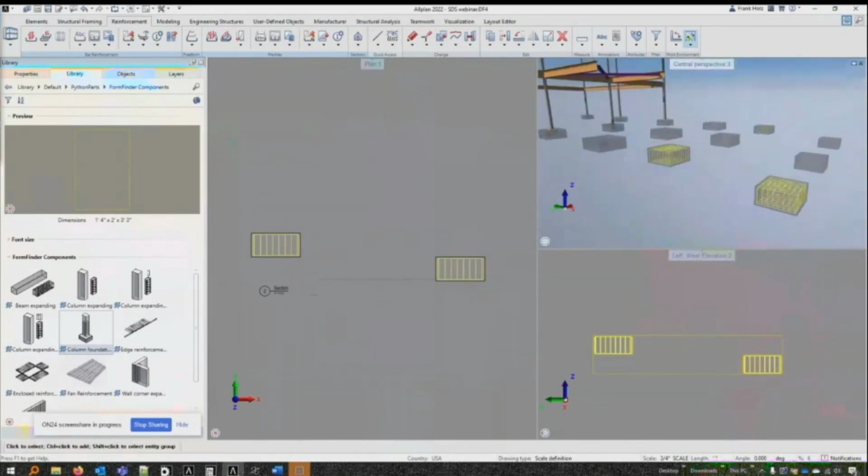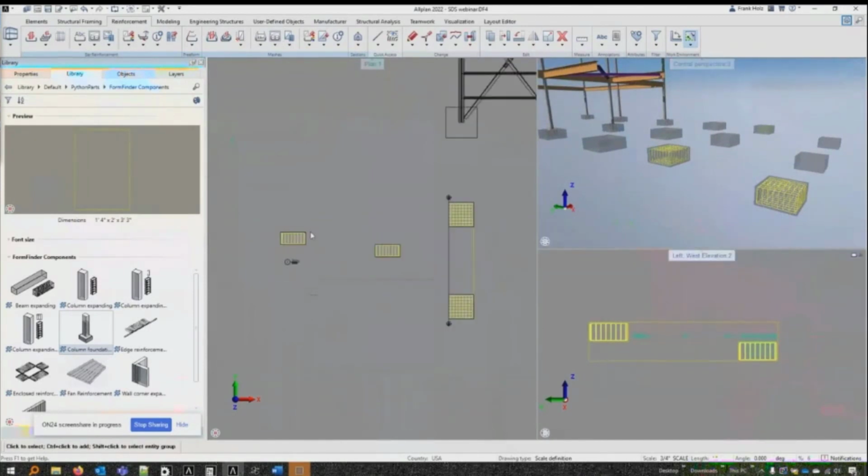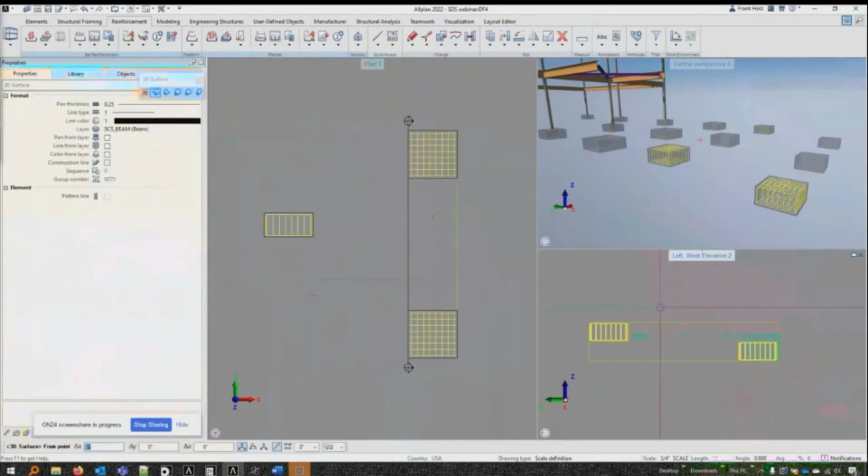All right, so now I'm going to create some fresh model here. This is going to be my step footing. So to do that, I'm going to come here to my west elevation and just start drawing in my 3D model. And I'm going to use a 3D surface tool. You'll notice it's right at the center. This is just where my elevation is being taken. I can move this work plane in and out of the X location if I want to.